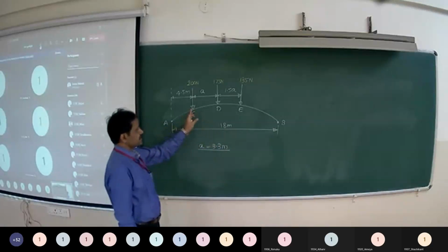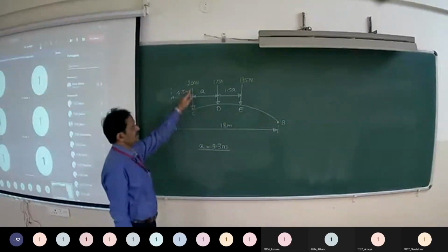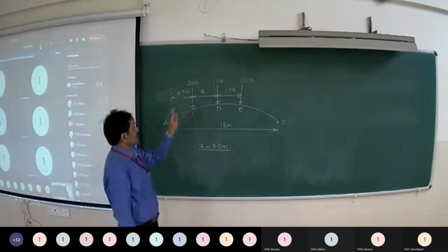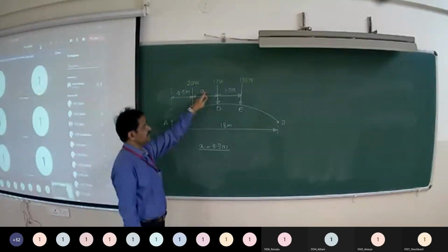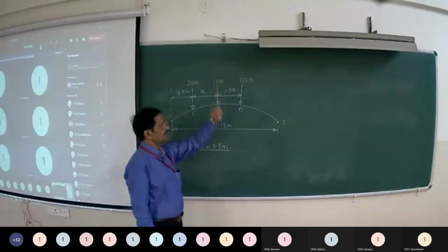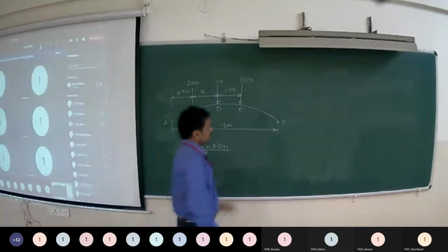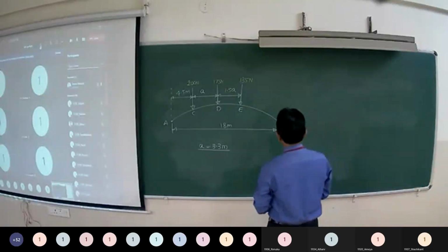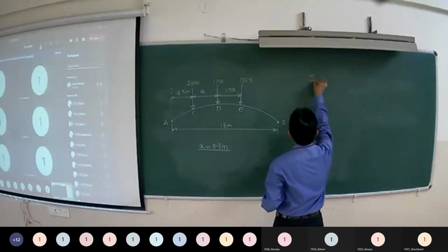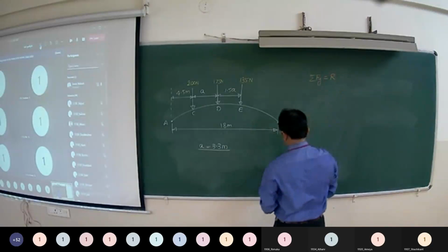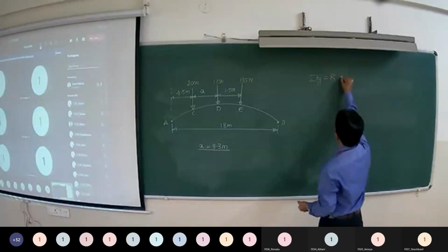Hikers are standing at C, D and E and their weights are 200, 175 and 135. The distance from A to C is 4.5, from C to D is a, equal to 3.3 meters, and from D to E is 1.5 a. Here all these 3 forces are acting vertically downwards. So taking the algebraic sum in y direction gives you the magnitude of the resultant.